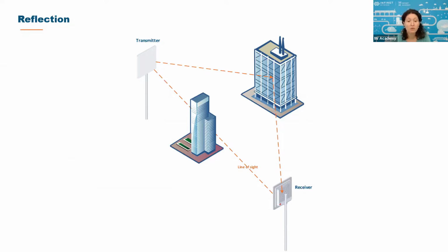This effect can also be used in order to establish the communication in non-line of sight conditions, as it can be seen in our picture. You can take advantage of the signal reflected by the neighboring building, but please remember that interference can also be destructive. So in a place where multiple reflections occur, like business centers or near the surface of the water, a careful analysis of the signal at the reception must be performed in order to evaluate the possibility of establishing an efficient radio communication system.